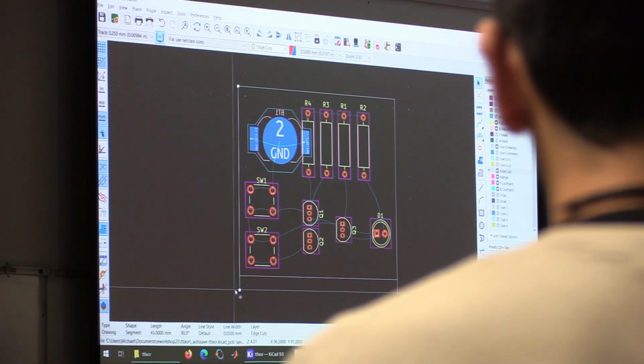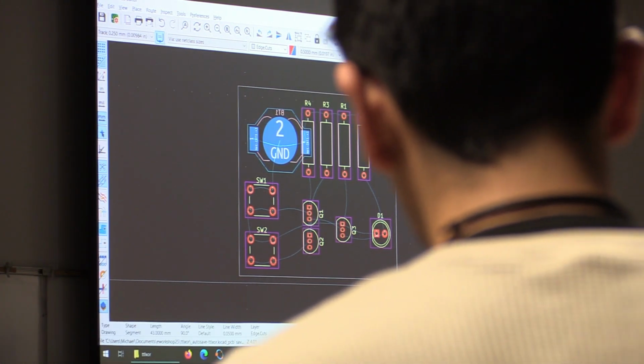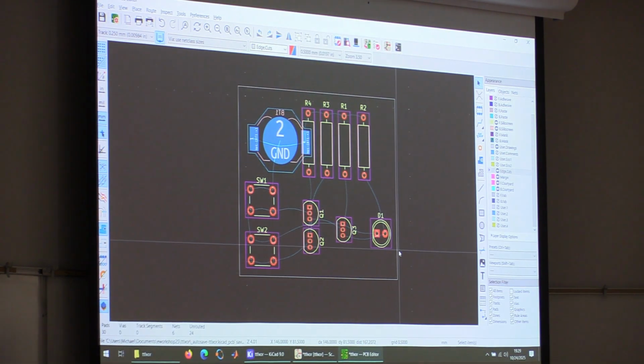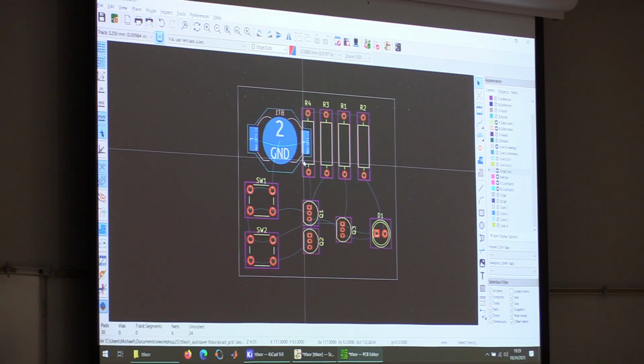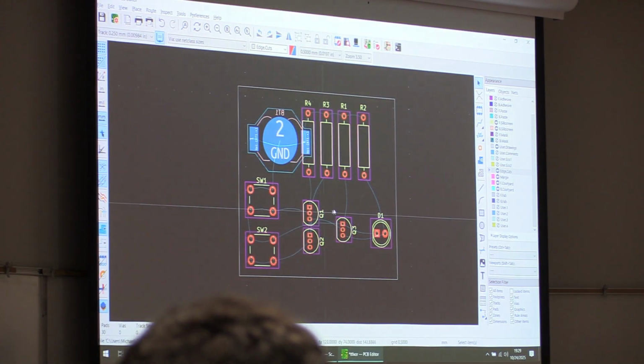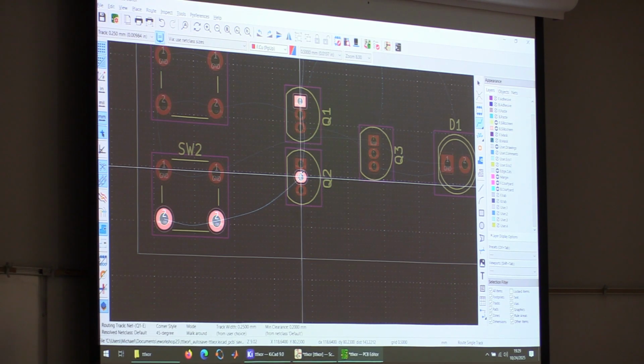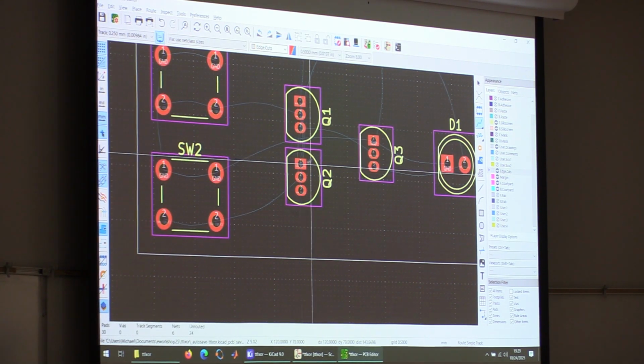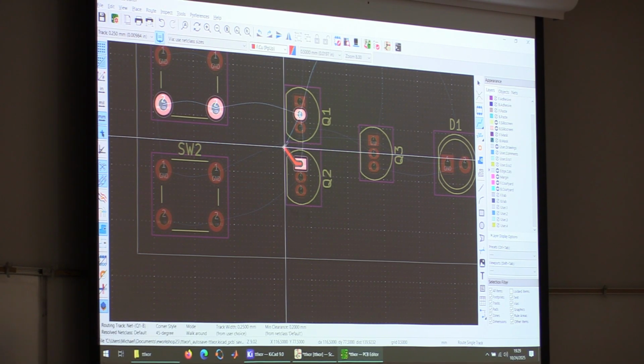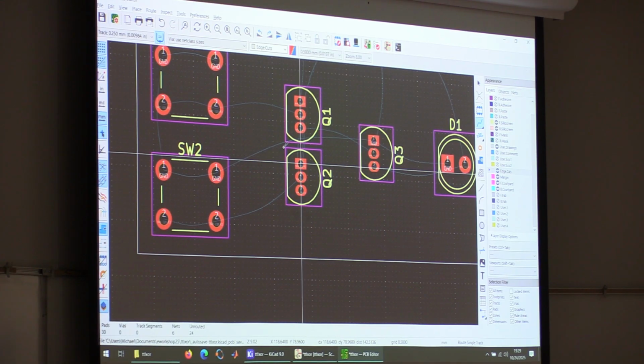What happens if I make a point, but it has nothing to connect to, and I try to make a wire? Which component are you on? It's Q2, the left thing. I have it oriented like this. We've got that pin, that pin goes there, this pin goes to this. If it doesn't have a connection going anywhere, usually that means that we haven't defined where that pin goes to. So if you go into your schematic editor and correct that, then it should hopefully fix it.